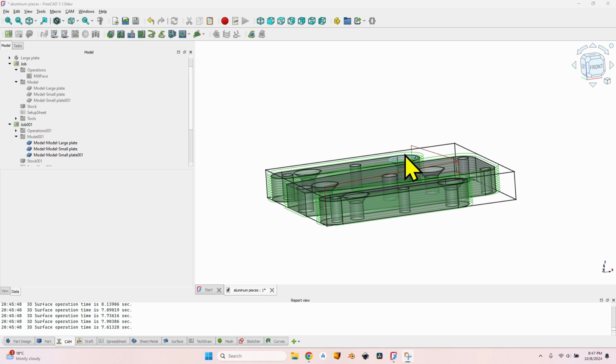I hope you will learn something from this video. I'm sorry for not being able to tell too much more about selecting the proper tool bit and the feed speeds and the spindle speed, of course, but as I've told you earlier, I think that is a thing that you will have to learn for yourself on your machine. Of course, you can take a look at some guides. You can also take a look at my videos to see what I usually tend to use, because my machine is a custom-made machine. It's not the weakest but also not the strongest. The tool bits are pretty normal tool bits. I tend to use 2 flutes tool bits for aluminum and 1 flute tool bit for wood and acrylic.